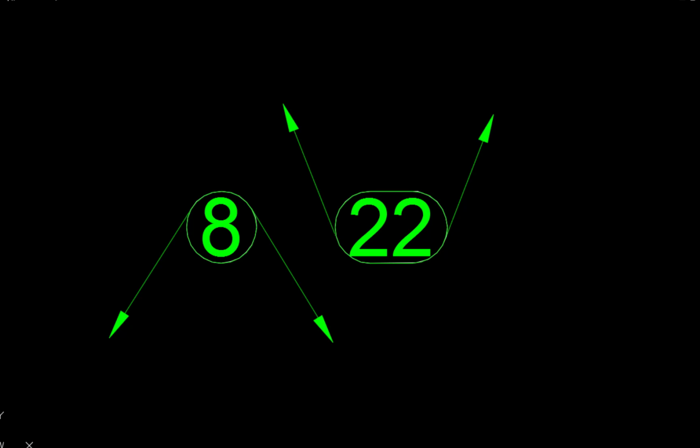The label also includes a leader that is tangent to the circle and a wipeout around the circle to obscure objects behind the label. Copy the label and leaders to the desired location and change the number as appropriate. The leader may be erased if not needed.